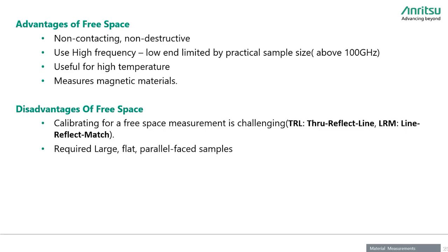Now, what are the disadvantages? The main disadvantage is the calibration. There is a challenge in calibration for the free space measurement, and we require LRL, LRM kind of techniques for the calibration of the setup.